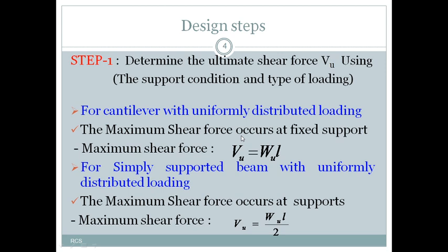If you want to practically design a beam where you exactly want to take the shear force, for this the code has given one provision that we have to calculate the shear force at the critical section of a beam. What do you mean by critical section? The section where the factored or ultimate shear force is calculated is called a critical section. Generally, as per IS 456-2000, this critical section will be taken at a distance d, small d, from the support.